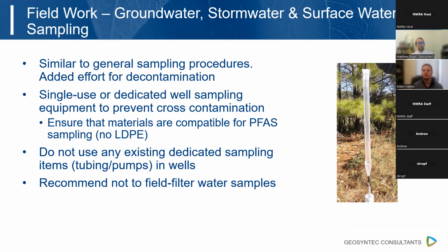So in terms of the actual field work for groundwater, stormwater, and surface water sampling, as we said, there is a lot of products out there that are certified as PFAS-free. The actual procedures are pretty similar to what most consultants or regulatory agencies would use out there. The only thing is that there's generally going to be some added effort for the decontamination. Typically for PFAS, we'd recommend single-use or dedicated well sampling equipment to prevent cross-contamination and also to cut down on that decontamination time a little bit.